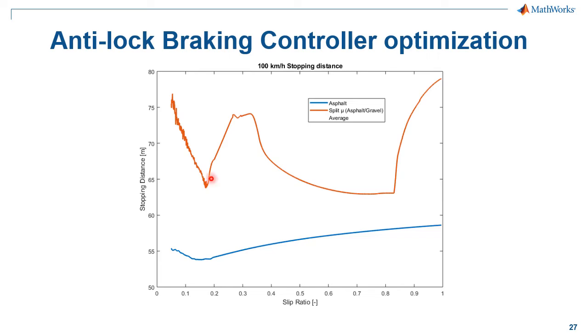As we can see, there is a clear minima in this location, and this actually corresponds to a minima on the asphalt. Since we want to have equal weight for these two situations and not have the controller select according to the situation, so only one controller controlling for both of these situations, we shall be using the average of these two graphs, which is indicated by the yellow dotted line, and selecting the minima from that curve. This worked out to be 0.17.